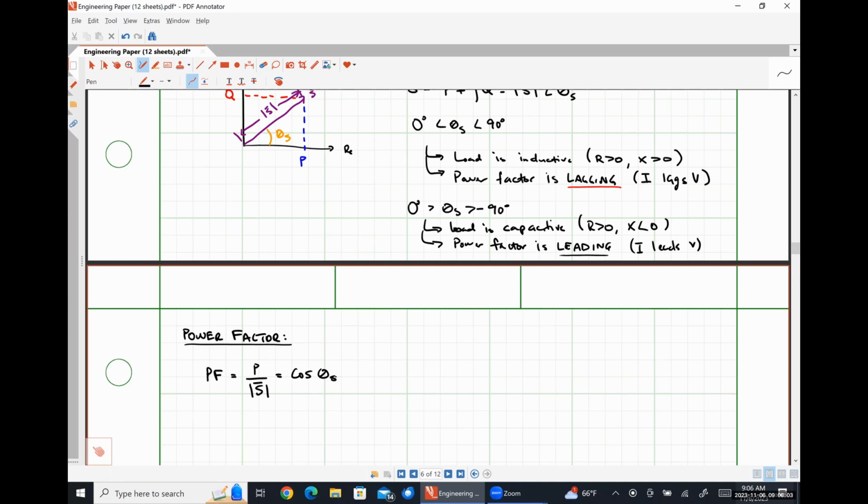So from the power company's standpoint, they typically want the power factor to be above 95% or so. Some places it might be a little less, other places it might be more. I think the highest I've ever heard was 97.5%, and the lowest I've ever heard of is 90%. But usually they want the system to be pretty efficient so that they're not wasting a bunch of money generating power that really doesn't get used for anything.